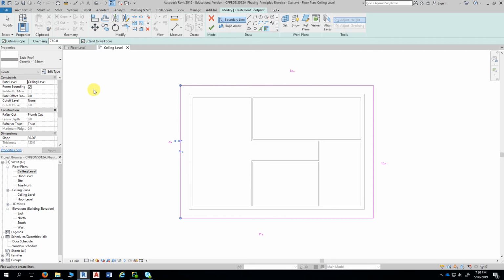Okay, I'm just going to hit the escape key a couple of times. So each of those sketch lines, the little triangle there, what does that signify or mean? Slope. Yeah, so that indicates that each sketch line with that triangle is going to contribute to the pitch of the roof. Now the pitch of the roof is going to be what?